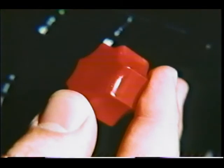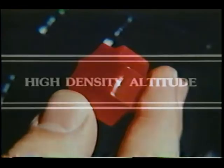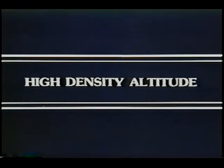Power, of course, is the single most essential ingredient. Therefore, every precaution must be taken to assure the availability of power when it's needed. For example, when you're landing at an airport with a high-density altitude, make sure your mixture's leaned as necessary to provide for maximum power. Why? Because you might need all the power available for a safe go-around. And remember, one of the key phrases here is high density altitude, because density altitude is the only altitude that's important to your engine.